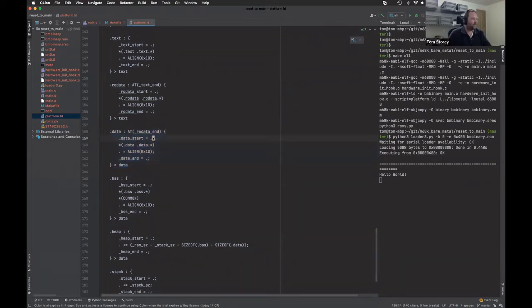But anytime you have a static variable, that will typically be allocated to a physical memory address, because that needs to hang around between function calls and that sort of thing. And it might also potentially have an initialized value when the application starts running. So any of your static variables, or anything that's not going to just be worked with on the stack during runtime, they'll all go into the .data section.